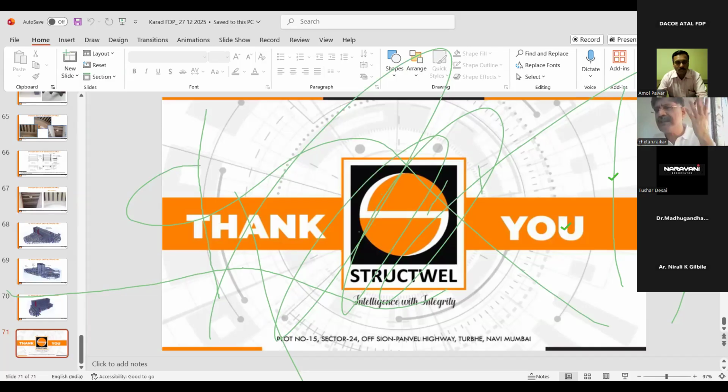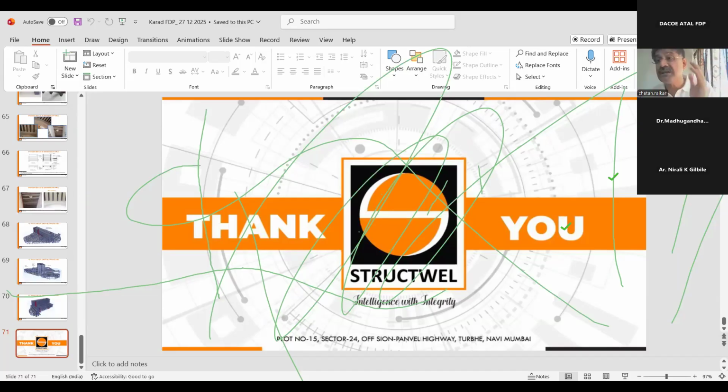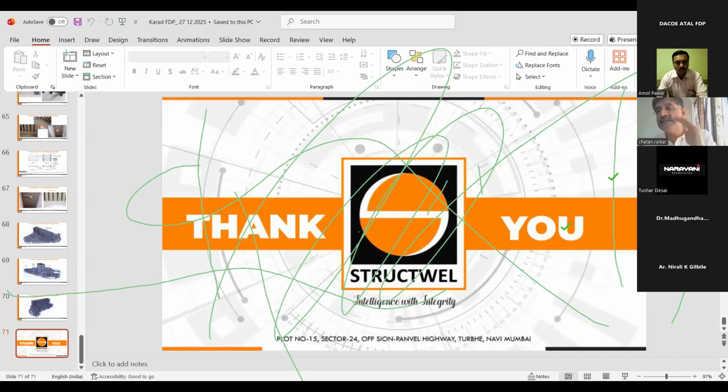And as I said, if it is not a very important structure, like last time I said in Rajwada, though 250 years old and an archaeological structure, instead of the vaulted brick roof, I went in for RCC slabs. Chakk RCC ची slab टाकली because it was above the false ceiling. So that's how you can bring the costs down logically and intelligently, and it is very safely permitted in English heritage techniques also. So, have I answered your question?